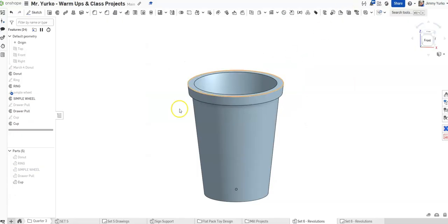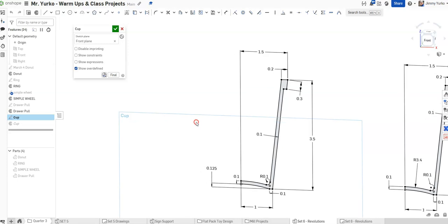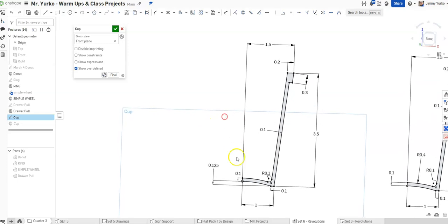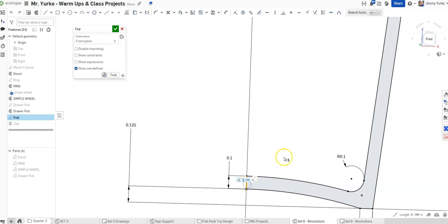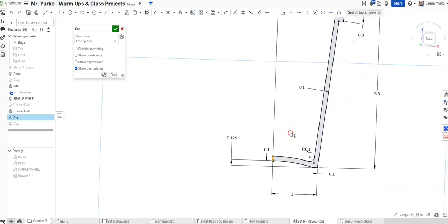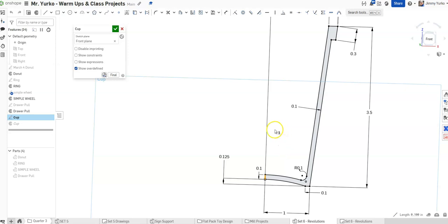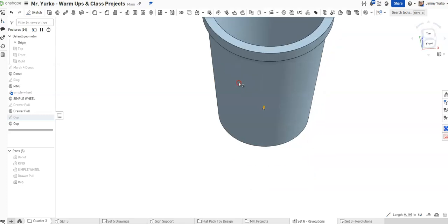So quick overview, we're going to go ahead and create this sketch of 1/4 of the cup, or at least what 1/4 would stamp out if you use it like a rubber stamp on the table. Let's create just this section area right there, and that is visible in yellow. Then we're going to use the revolve tool, revolve around this axis, and we're going to revolve full 360 degrees, and that will give us the final cup, just like you see here.